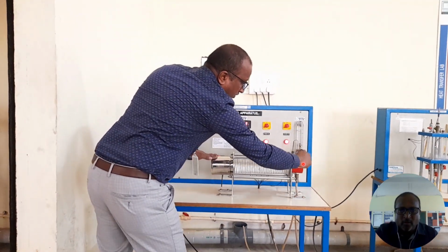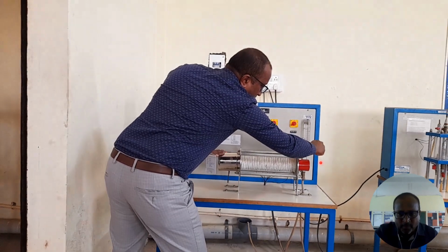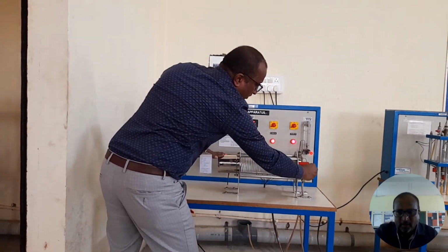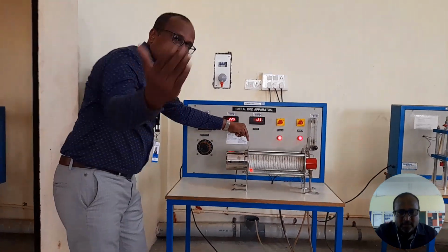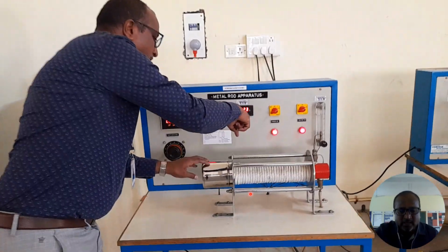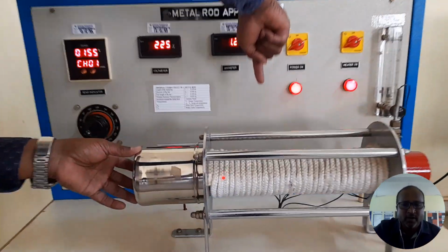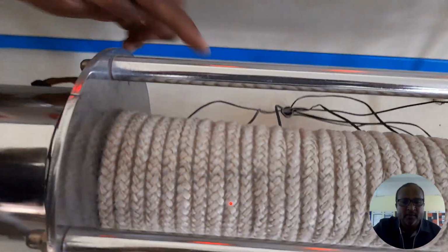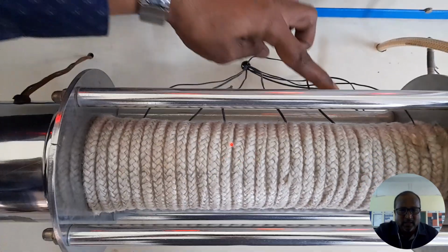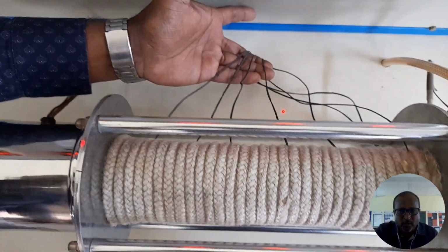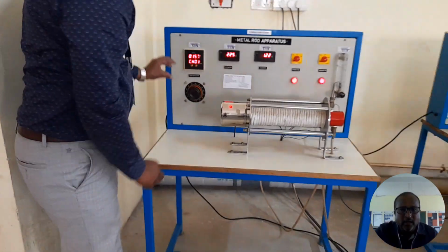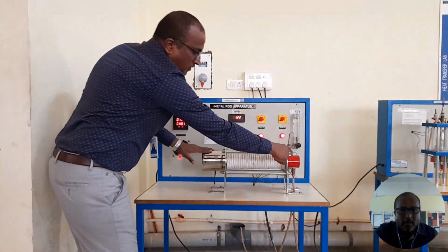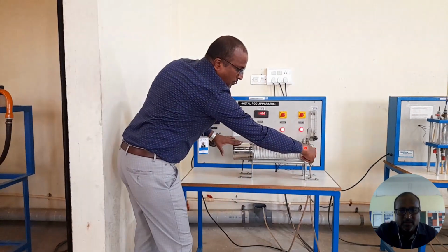From the other end, I am going to take the heat out using the cooling water by adjusting the flow rate here, right? And here the temperature readings at different points on the rod. As I said, thermocouples are placed at different intervals, equal intervals here, you can see here. And these are the wires which are attached to the thermocouples, and they will let us know the temperature at those points on the rod, and that can be read on the digital meter provided here, from this end to that end.